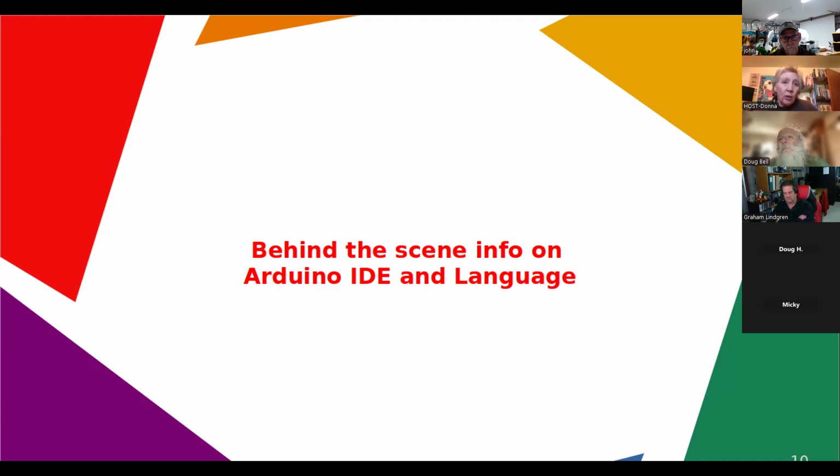So that's one thing: if you start looking at the way that the projects are defined, the downloadable that's generated, and then eventually downloaded into the board, things are going to look different. And one of the main things is that .ino file instead of .c and .h. Okay. Tool chains. The tool chain is a modified version of a standard open source compiler package called GCC.